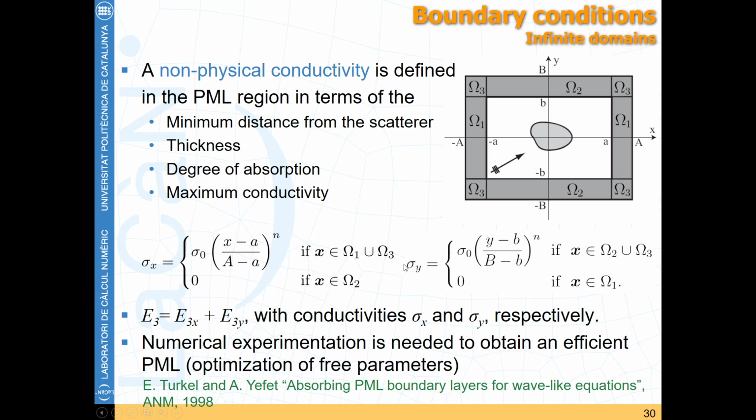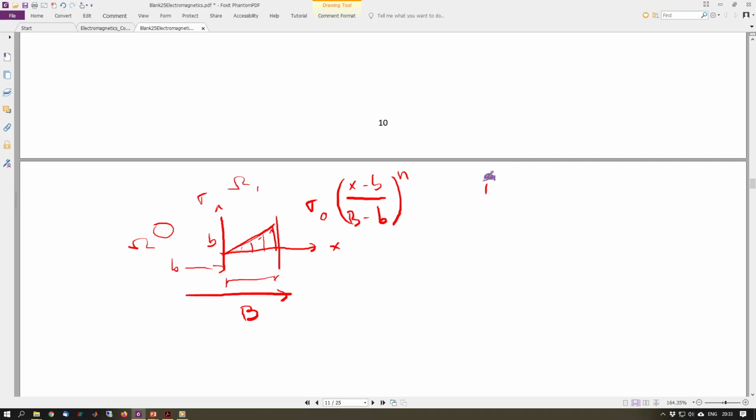We are going to use this absorption in the case of the transverse magnetic mode that we have. So in our x and y, we're going to have H1, H2, and we are going to have our E3. That's how we would simulate. So we have absorption for the E3, and we decompose our third mode into two quantities. One, E3x, is going to be absorbed along this x direction as we go through that domain, but the E3y is not going to be absorbed along this domain.